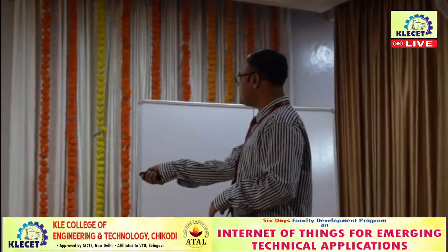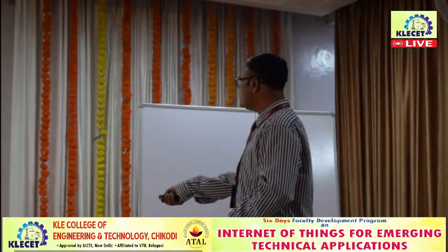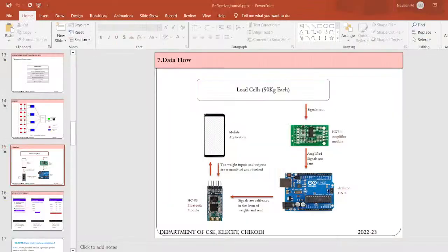Again, there is a mobile app through the HC05 Bluetooth module. We are going to interface it to the Arduino Uno board. Then here there is an amplifier. So whatever load cells are there, they are going to send a signal to the amplifier module. From the amplifier module, it will come to Arduino Uno, and through HC05 it will be displayed on the mobile phone.